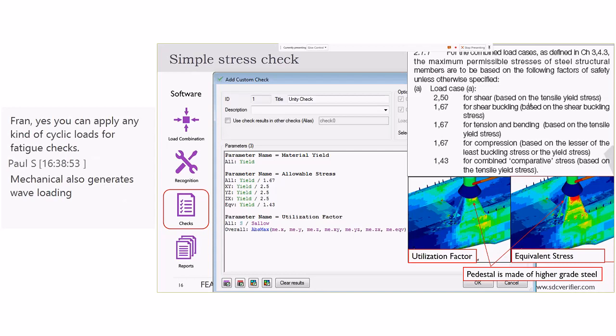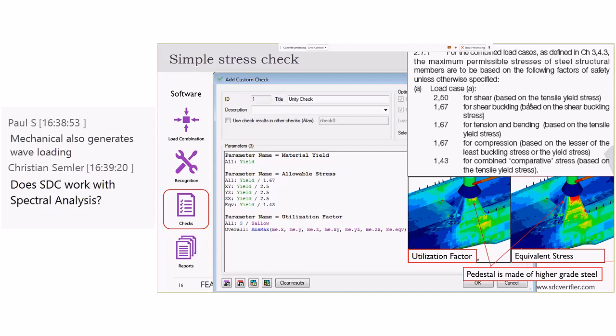Walter, I think there's a slightly bigger question there. Fran's asking, can fatigue be calculated with wave loads? So FatJack, for instance, and you mentioned that. It was very specific fatigue for tubular or beam connections. And I think the big differentiator there over conventional fatigue is that it had stress concentration factor formulations built in. So that's a big area, and I know we've historically talked about making an ACT extension to allow that to happen. Is that in your plan?